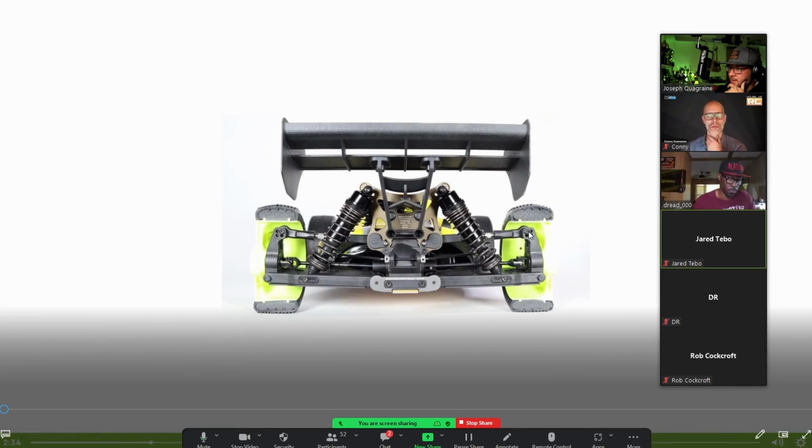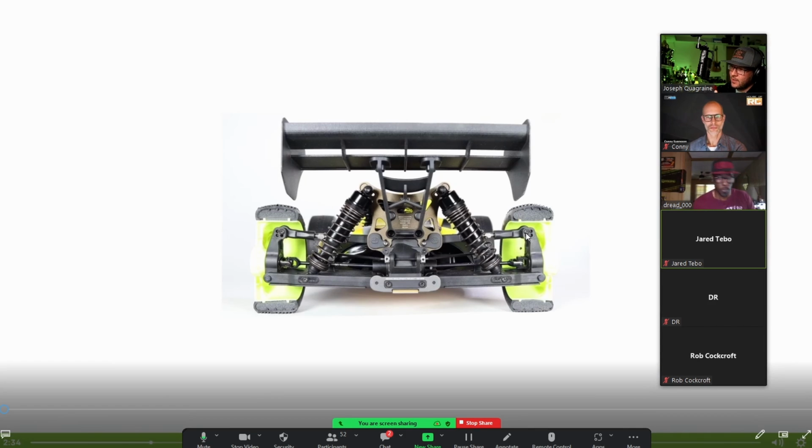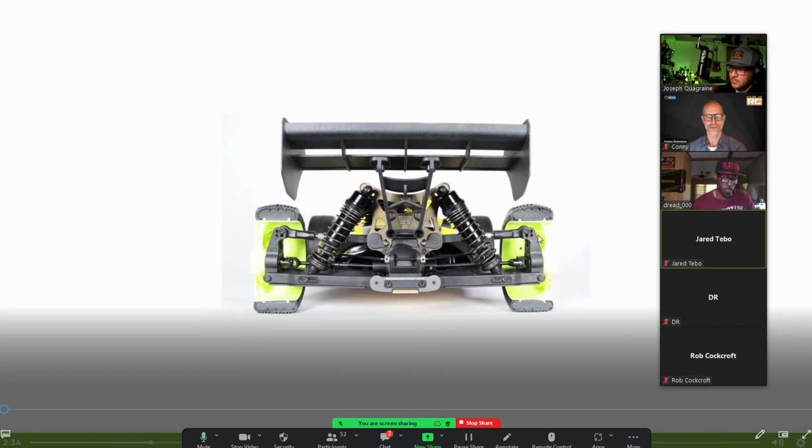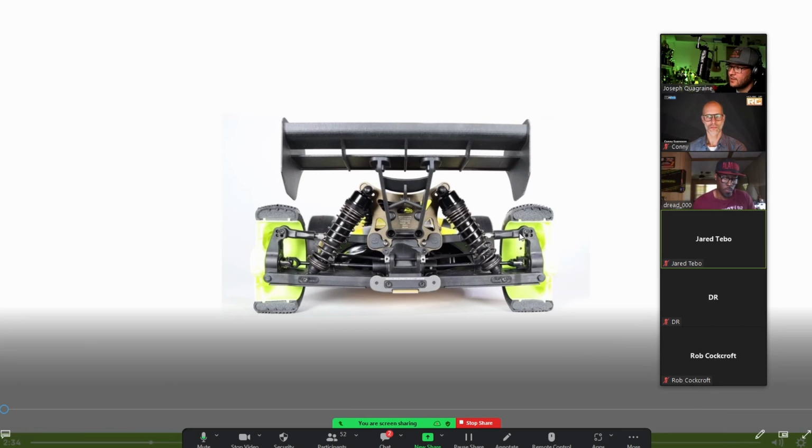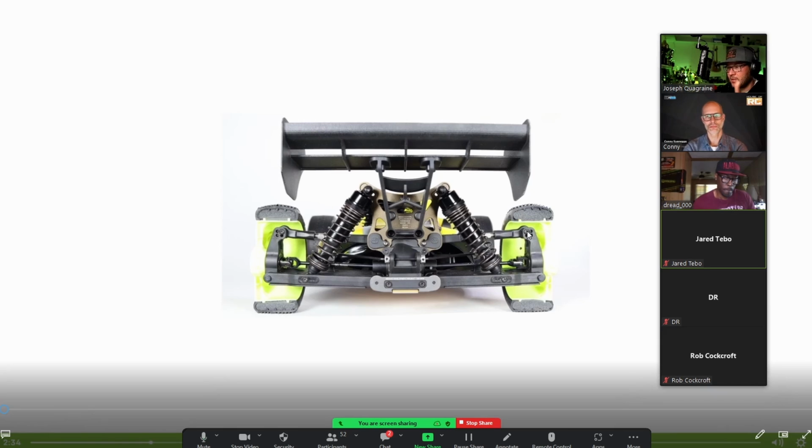What this does is I purely think about the length of the link as, do I want things to happen quickly or slowly? A short link, things happen more quickly, there's more response. A long link, everything is smoother and more calm. So again, initial versus overall grip. Short link for initial grip, long link for overall grip. So that's one, the lower arm height for support. Two is the upper link length for fast or slow responsiveness.